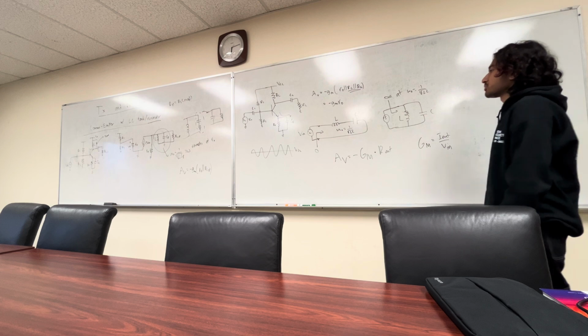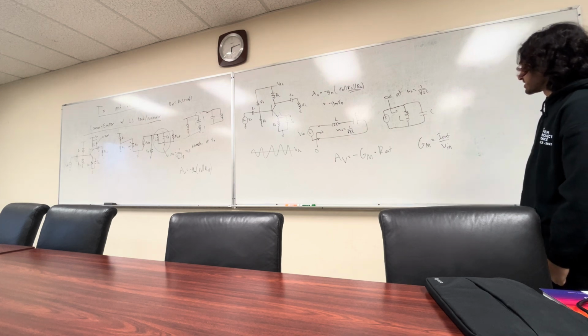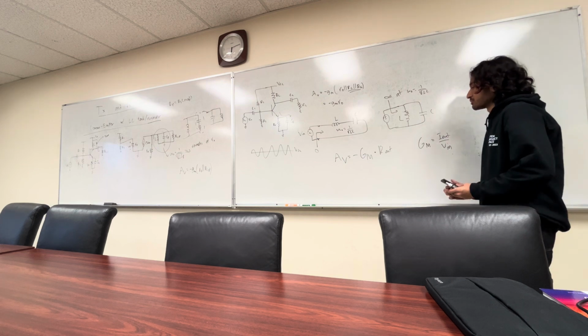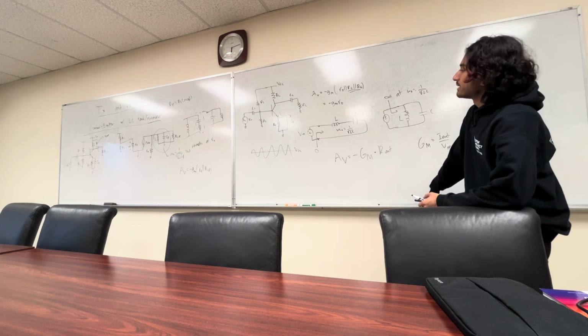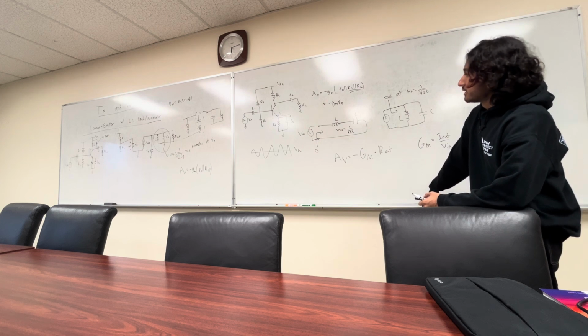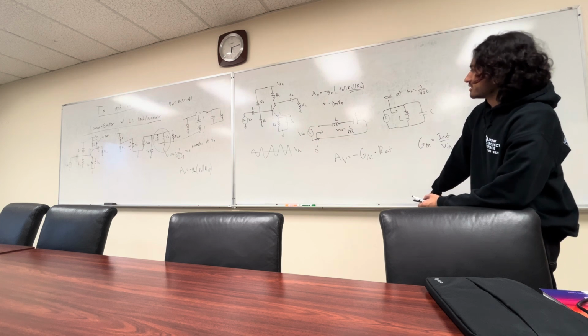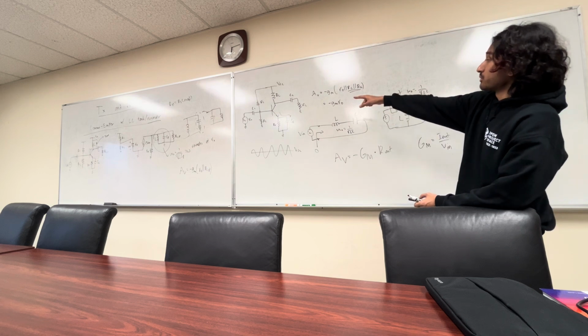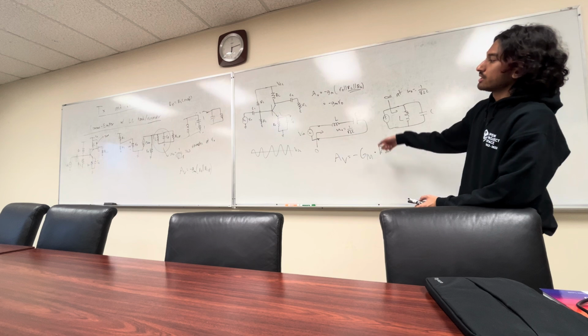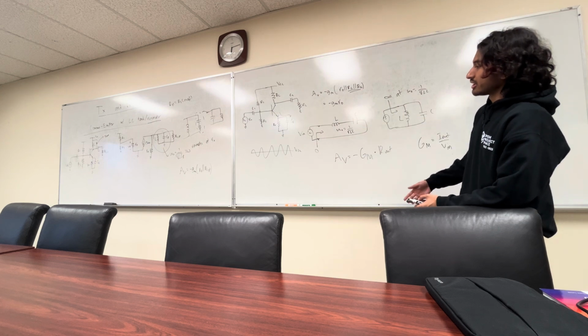This is something you'd probably talk about in 115B, I suppose. But this equation always holds. I'm going to talk about some more next lecture and some nuances, and although it's very useful, it hides some of the detail that you might not see. But we look at this equation directly. Before, we have R naught parallel RC parallel RL, that's your R out. And now it's just R naught parallel with RLP.